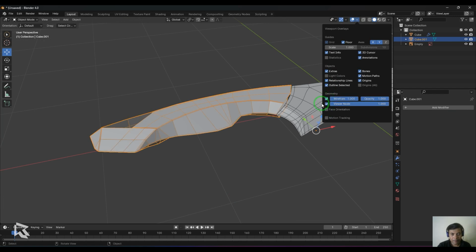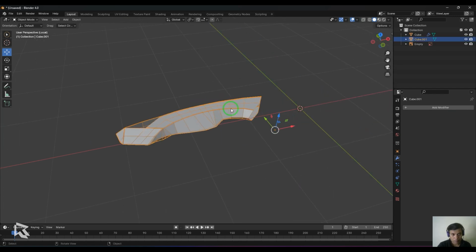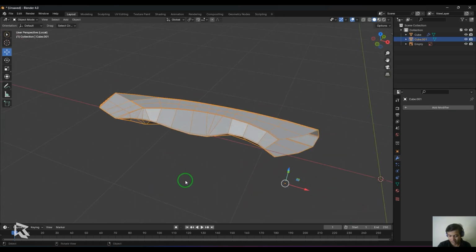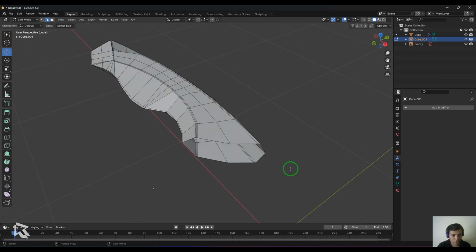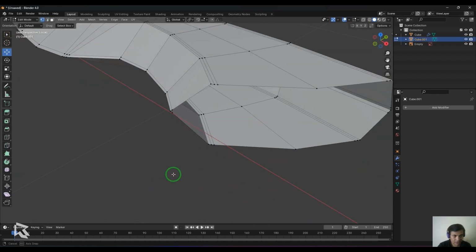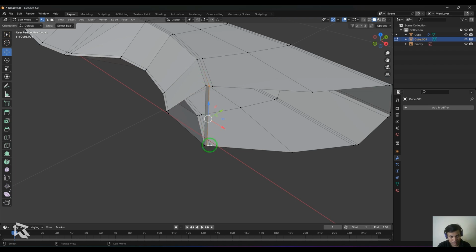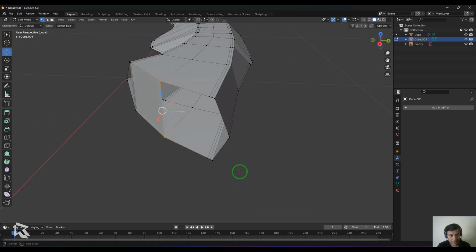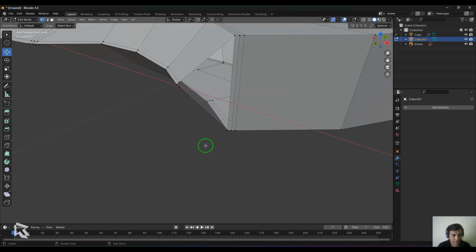Now I've isolated this model by selecting it with the forward slash, and this hole has to be filled. So I'm going to select the vertex component. I select only 2 points here on the top and 2 points on the bottom, press F. Then select only the 2 points, one on the top, one on the bottom, press F, and start filling those points until it's filled correctly.